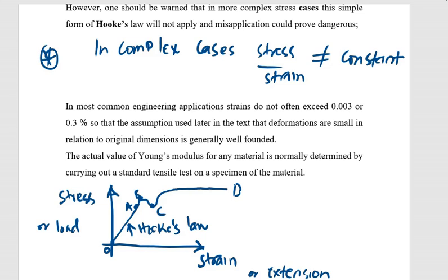Hooke's law is valid, and it means, therefore, if I wanted to find the Young's modulus, which is a constant for this kind of material, it could be for ductile materials, for example, a copper wire, or any other particular material which can be rolled into a shape, when we plot the values of stress against strain, as long as the elastic limit is not exceeded, a straight line graph is going to be found.